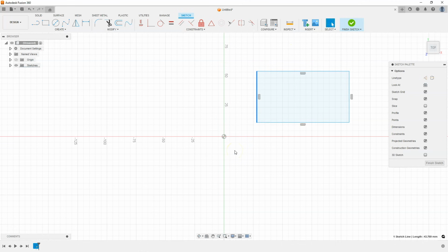Location can be relative to other geometry or to the origin, and we use either dimensions or constraints to determine the location. And here what you see, these symbols next to the lines define constraints, and checking or unchecking the constraints turns the visibility of constraints on or off.